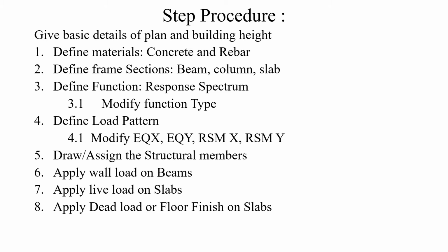And we have to modify the function type. In the modification of the function type, we will be provided with the zone factor and the soil type. Depending upon your project, depending upon the details which you have available, you have to modify the function type.